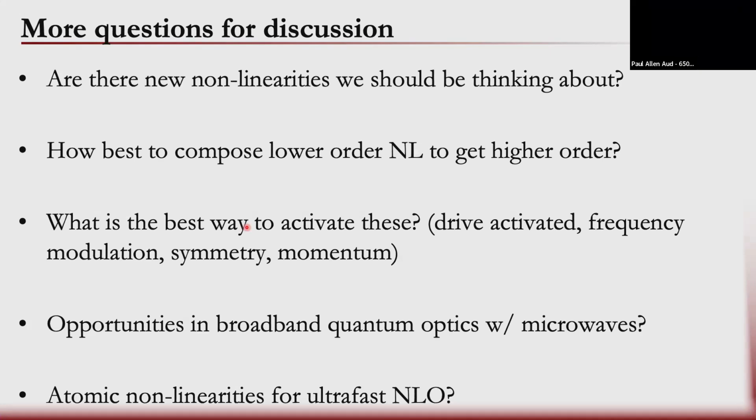I mean, all the paramps have this critical slowing down, and that's just assumed. We do the impedance broadening to get around it. So we impedance broaden to get around the steady state slowing down feature in the modern cavity-based paramps, but we don't tell you how long it takes to ring them up.